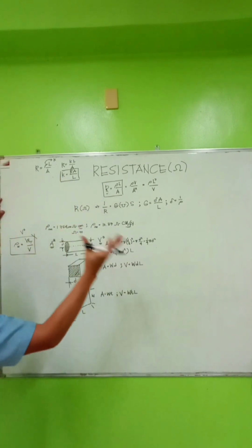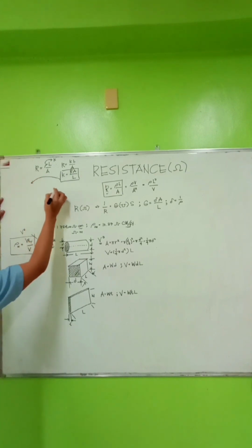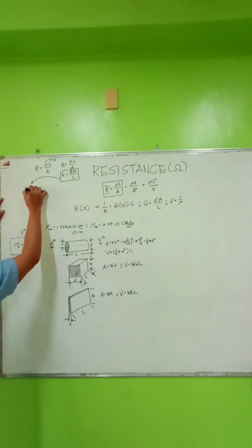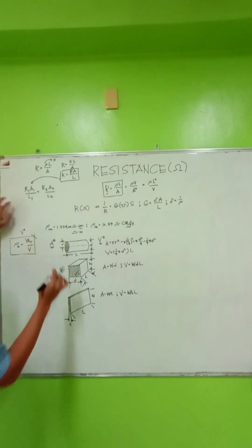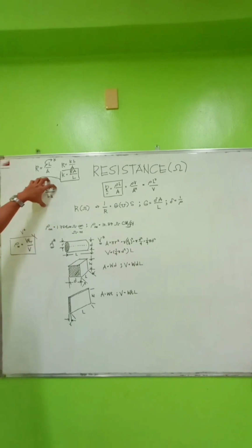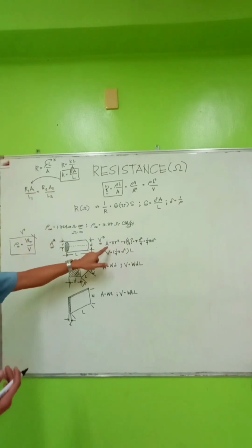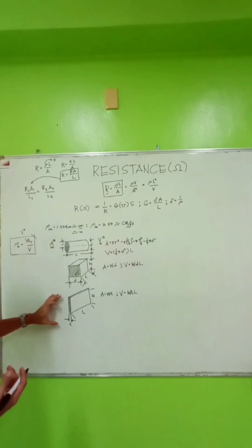For example, if you have two different conductors, you can transpose that condition to R1 times cross-sectional area 1 all over the length of your first conductor, equals R2 A2 all over the length of your second conductor. Here, make sure that you deal with the cross-sectional area properly. You need to identify your cross-sectional area accordingly, if it is a cylindrical, a cube, or a bus bar shape.